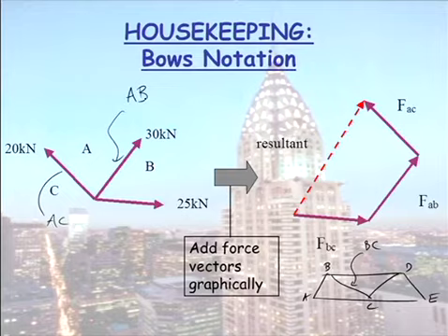And back in the old days when we did method of joints and we didn't have calculators, we would actually use protractors and rulers and draw these as vectors. And we would see in this system here, when you add your 3 member forces together, because they don't all come back to a point and form a closed triangle, we have a resultant force in here. So in this instance, there is no equilibrium in this system.